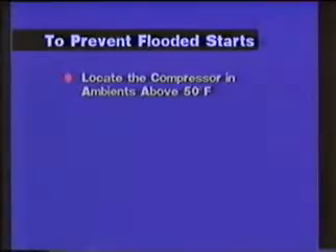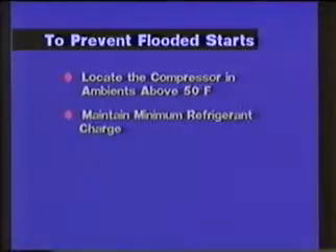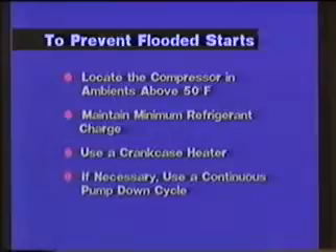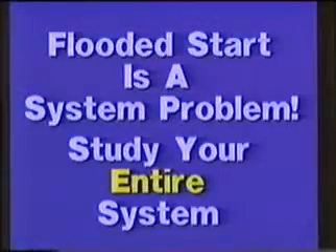Let's summarize. To ensure that flooded starts are not a problem, the service technician should: 1. Locate the compressor in a controlled ambient above 50 degrees Fahrenheit if possible. 2. Do not exceed the recommended maximum refrigerant charge and maintain an adequate oil level. 3. Use a crankcase heater. 4. If you feel conditions make it necessary, install and use a continuous pump-down cycle. And finally, study your entire system during the off cycle. Determine if it is a candidate for a flooded start problem. Alter your system accordingly. Flooded start problems can be avoided.